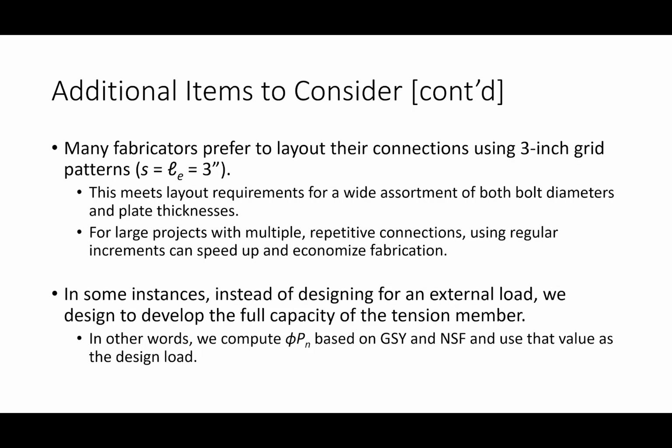The reason is that a 3-inch spacing for both bolt spacing and edge distance meets the layout requirements for 3/4 inch bolts, for 7/8 inch diameter bolts, and for 1-inch diameter bolts. So it's a nice pattern that meets spacing and edge distance requirements for a wide array of bolt diameters.